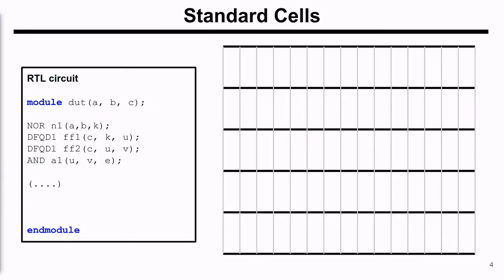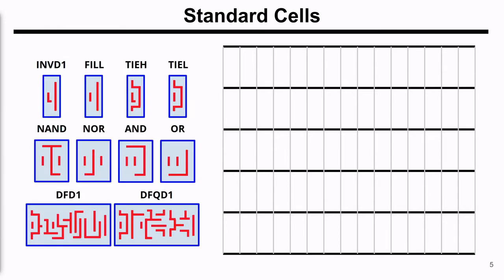To create digital circuits, we execute several processes including synthesis and place and route. On the right is a synthesized netlist. We will be placing and routing using several grids pictured on the left. For this reason, we use standard cells. Several cells perform different kinds of functions and logic. The synthesizer previously mapped the RTL circuit to those cells, offering a netlist whose behavior resembles the intended behavior supplied in hardware description languages. The next step is to perform placement and routing to implement this circuit in VLSI.